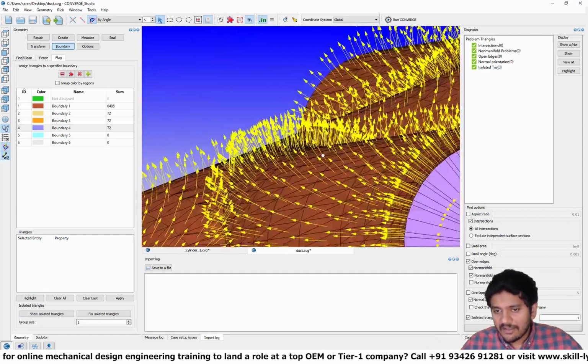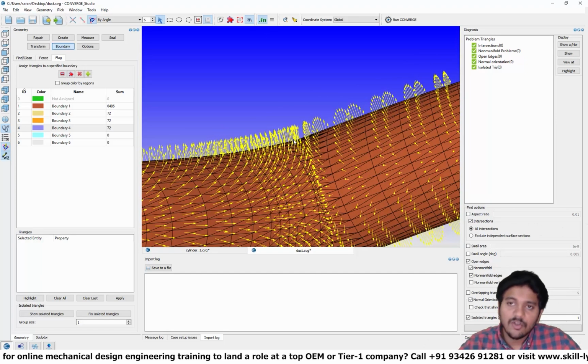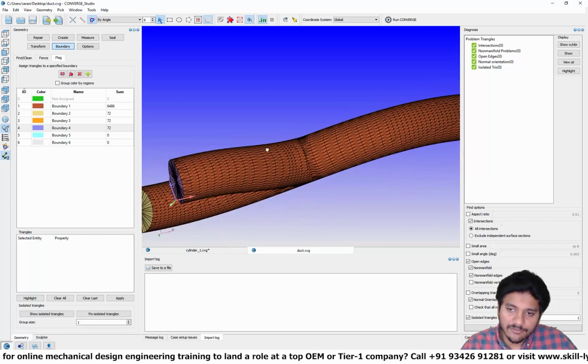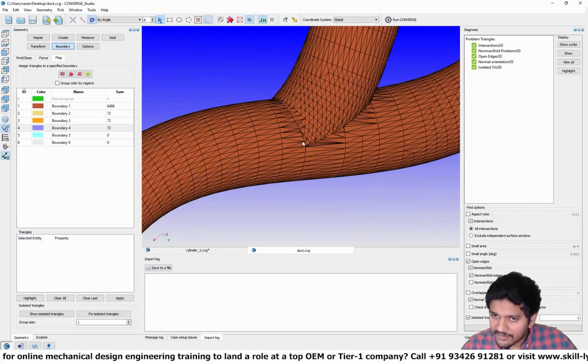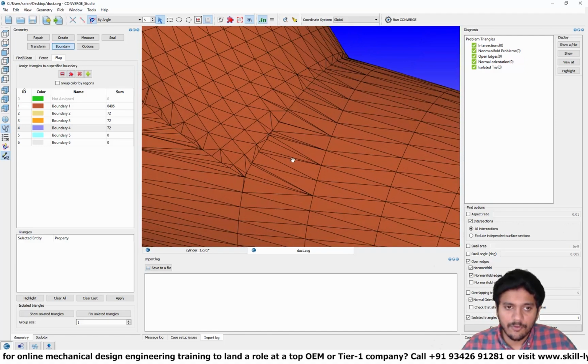The problem that's occurring here is that the normals have a smooth distribution and the direction of the normals does not change a lot. Because of that, the angle method has a very hard time trying to figure out where the edge is. On the other hand, we can see that there is a characteristic edge here, and I'm just going to create a simple boundary fence.